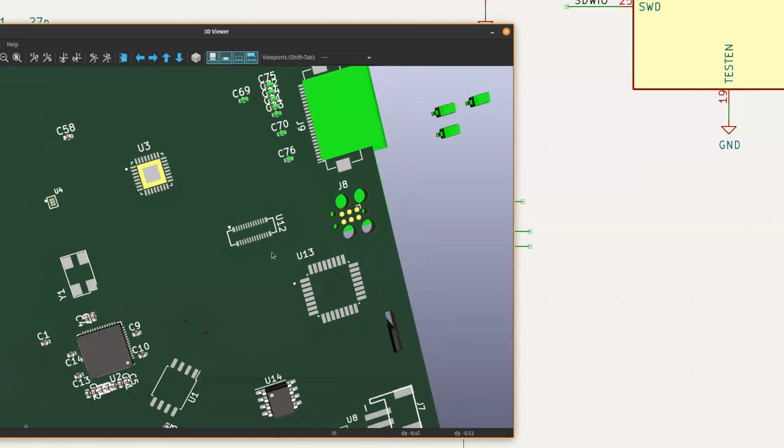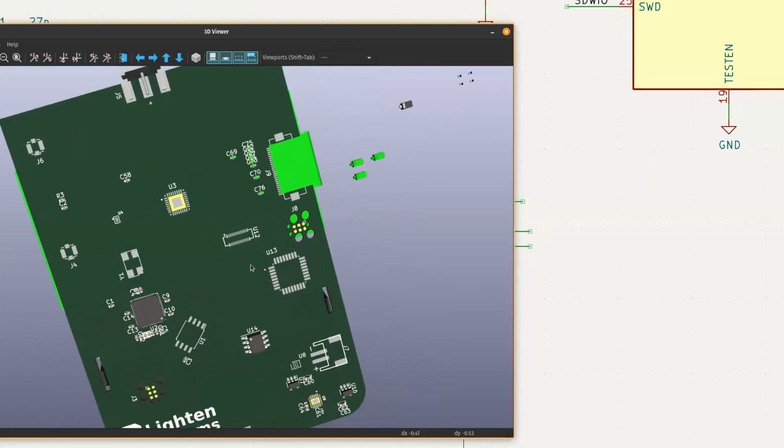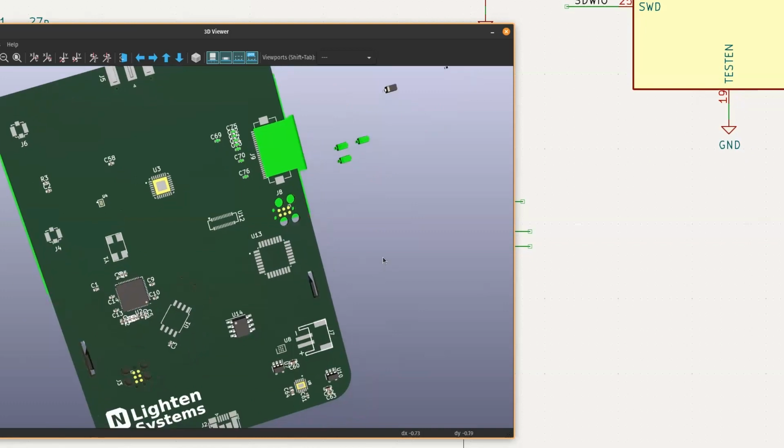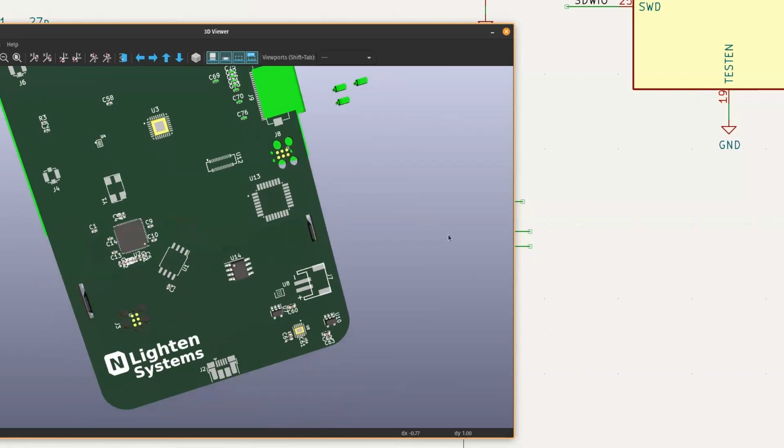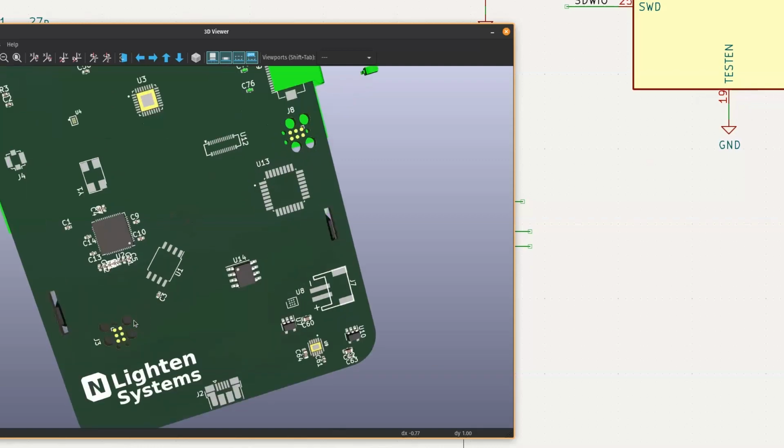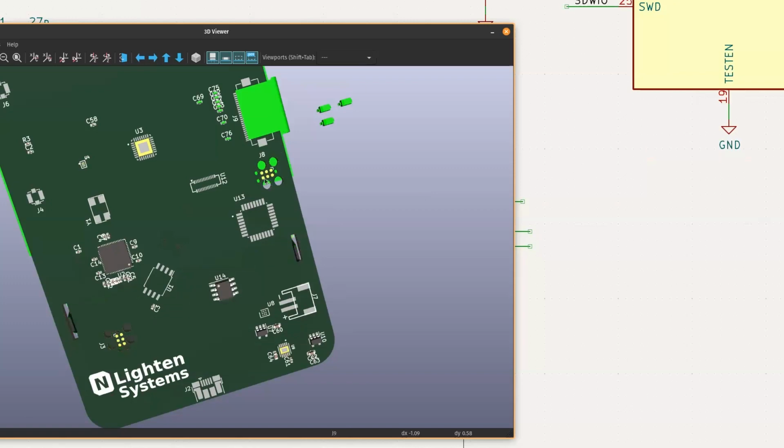So this is just one of those tag connects. If anyone doesn't understand, those are connectors that kind of lock to the board and use pogo pins, little springy pins, to connect to the board. And they're big enough that if you don't have one of those connectors, you can also just solder on through these little pads. These connectors are kind of expensive, by the way, they're $60 each. But once you have one of them, you'll use it for everything.